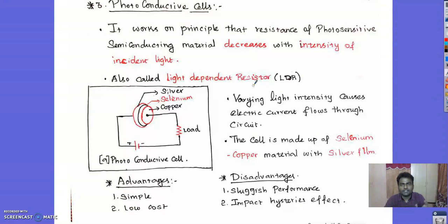At the bottom, it has a dark surface and a lighter surface. The lighter surface will reflect more light, whereas the dark surface will reflect less light. So with the help of this phenomenon, this LDR is used to follow a particular track, and your robot will move only through the track. If it is going to a high reflecting surface, the sensors will make it move towards the low reflecting surface, and it will follow the low reflecting surface alone.